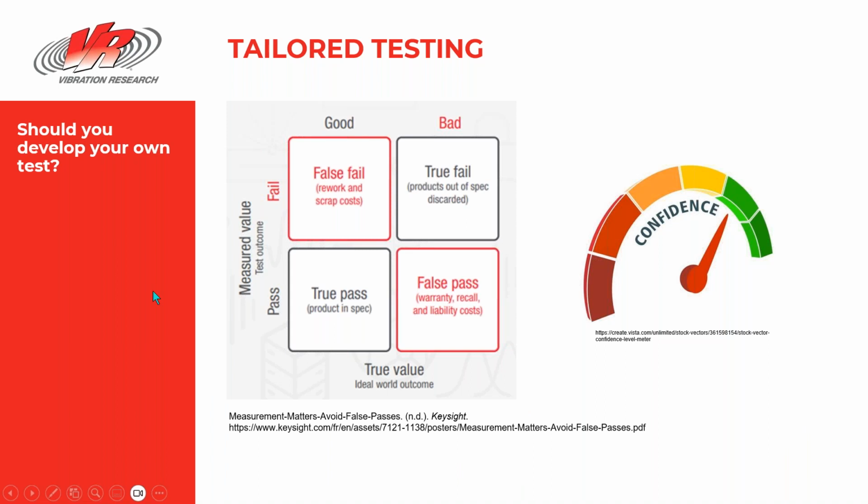So the issue with test tailoring is obviously making sure that you don't get a false pass or a false fail. You might measure environments, but you don't know what percentage of life customers spend doing different speeds or different levels, or how big the potholes are going to be in all the different areas of the world. So this is the kind of issue associated with test tailoring and your confidence in your test level.